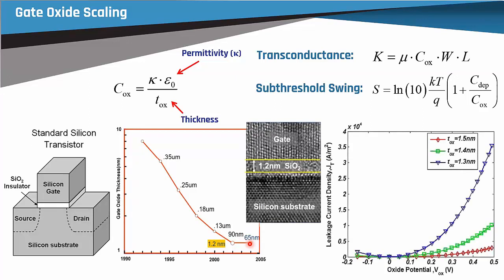And so our transistor, instead of just going from the source to the drain, now we have leakage current, especially if we go any smaller than that, going from the gate to the channel or to the substrate. Just so you understand, it's about 6 atoms or something of silicon dioxide to do this. So this was infeasible, okay? And that was another thing that was supposed to break Moore's law.